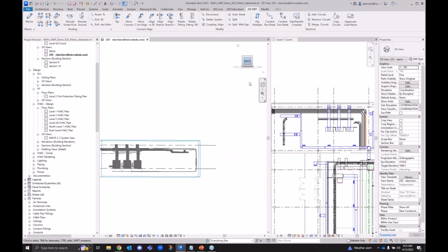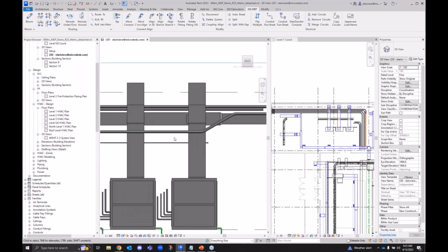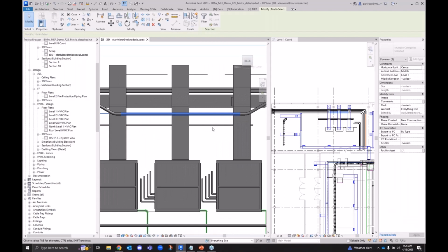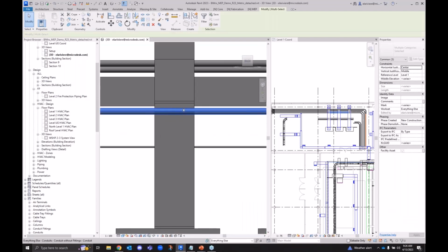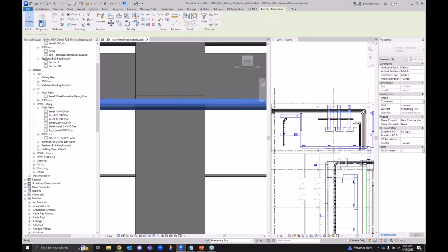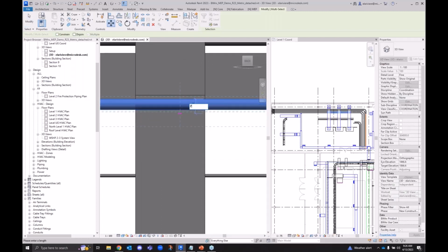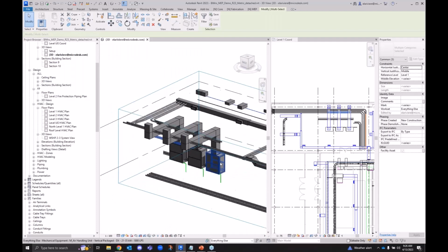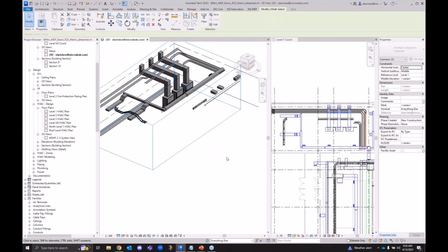A really cool note here, right? I'm going to keep hammering how powerful these 3D views are. If you want to move these things after the fact, you can actually even use the nudge arrow keys on your keyboard to lift these things up. If I wanted them to be an exact height below that duct, you can use your move command to lift it up, use your move command to bring it back down again. And maybe we want to make this 100 below. Incredibly quick to make those changes in a 3D view, all enabled through use of Naviate.